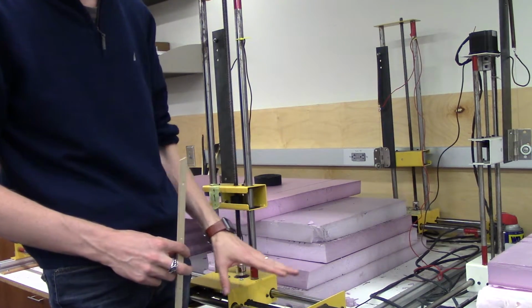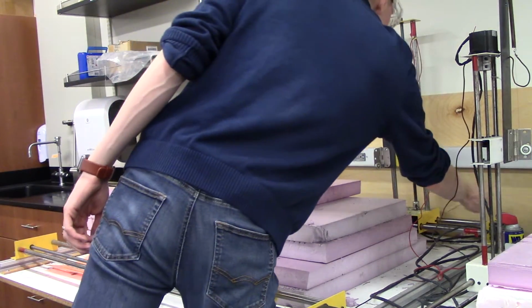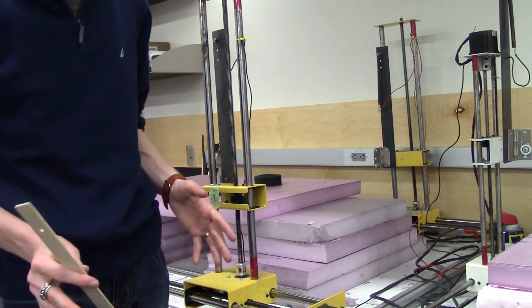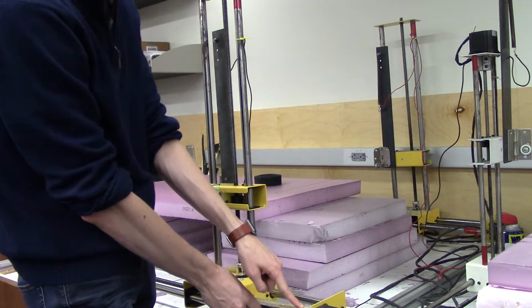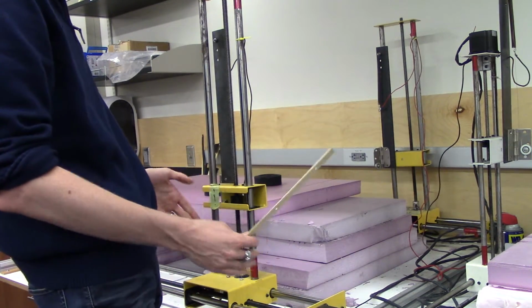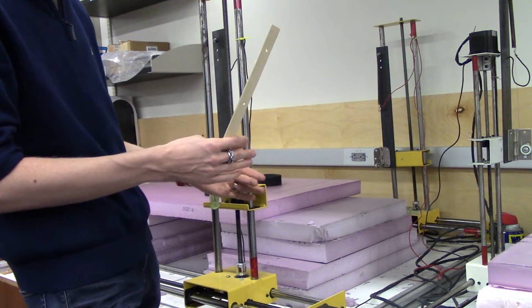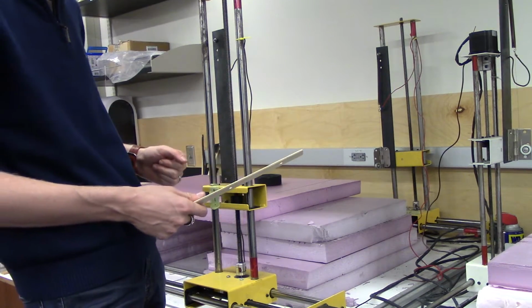Normally it's easier to handle the close side versus the far side, and so I'm going to reach over to the far side and measure a distance of 24 millimeters. On this side, I'm currently at 21 millimeters, which means I need to move this back farther so there's greater distance, and the distance on both is the same. That way we don't automatically build in some sweep where we don't want to be sweeping our airfoil.